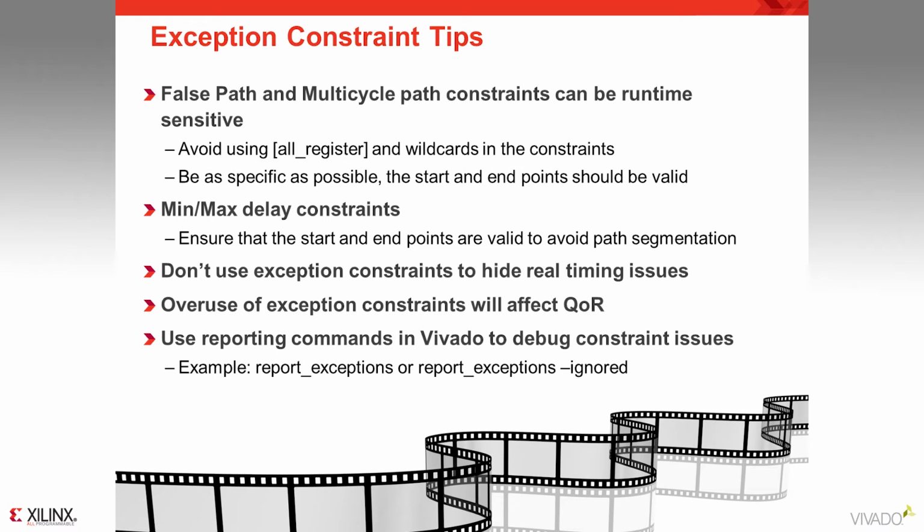Debug constraint issues by using the various reporting commands available with the Vivado design software. For example, use report exceptions ignored to debug and validate exception constraints.